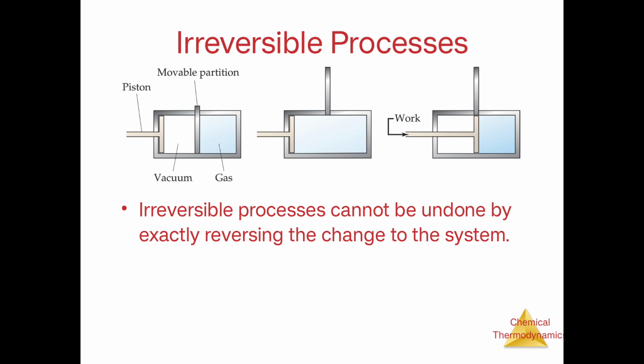When the partition is open, then the gas will fill the entire piston or the cylinder. So the work or the energy will be considered with respect to the movement of the piston through the movable partition. In such cases, the gas and the process of the gas inside a piston and cylinder will be considered as an irreversible one,